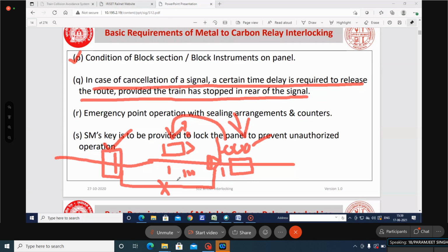1 kilometer, sir. So suppose a stop signal is there. If the information about the aspect of the signal is given at the normal braking distance, then if he knows the aspect of the signal, he can start controlling the train, so that if he applies the normal brakes, it will stop at the foot of the signal.